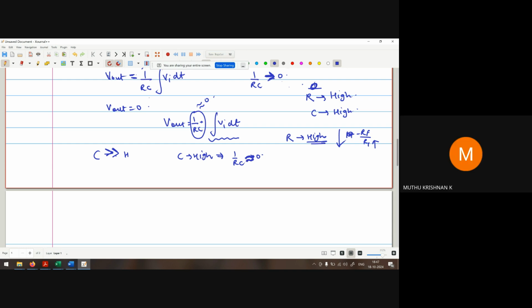But sir, when we add the capacitor, we are removing the feedback for DC, right? Yes, exactly. So if the capacitance is not so large, should we add another resistor just for the DC component so that it can also have feedback? Yes, we can do that also.